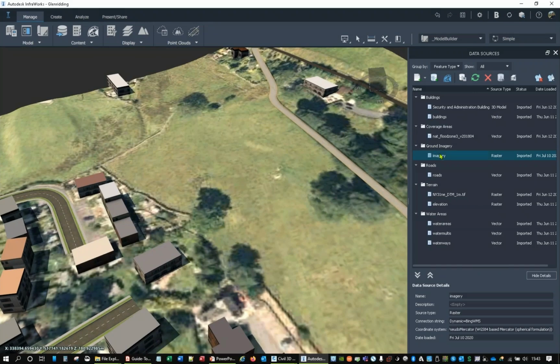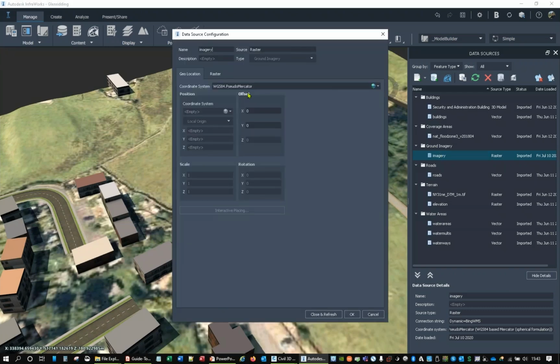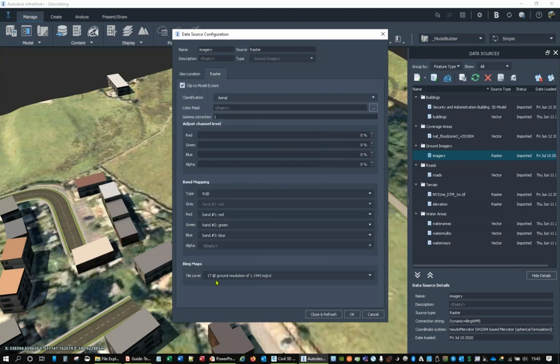If we go in here, it will tell us them resolutions, which is really nice. This is exactly the same for all you AutoCAD users, Map 3D, Civil 3D. Anybody using AutoCAD, it's the same source. And in the raster, you can see that it's at level 17. And it tells you it's 1.19, on average, 1.19 meter per pixel. So that's the resolution. But you can improve it.